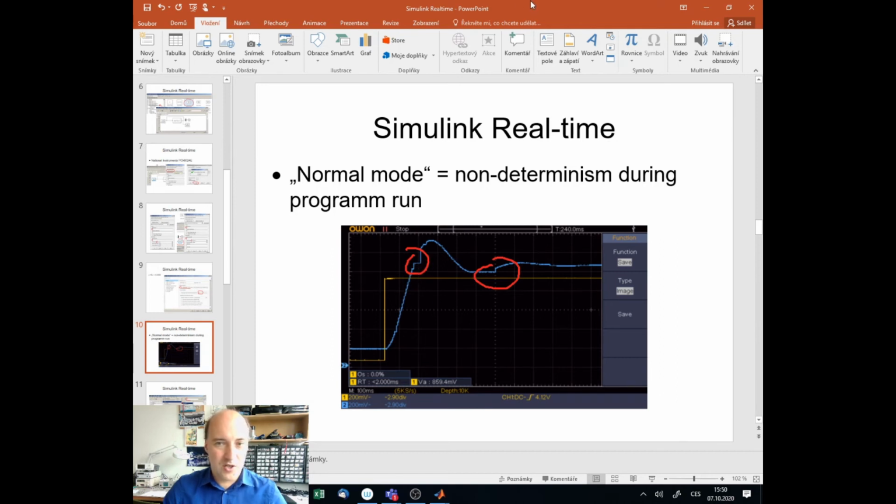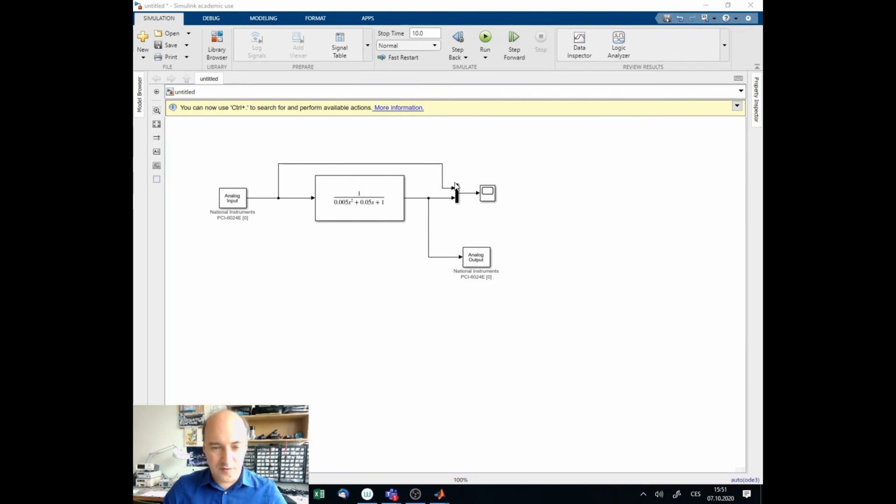So sometimes if you have a very simple code, it will run faster than in real time, like it's the case here, or if it's a really slow computer or very complicated system, it will run slower than in real time. Now we can of course accelerate the code here in MATLAB by actually compiling the Simulink code.